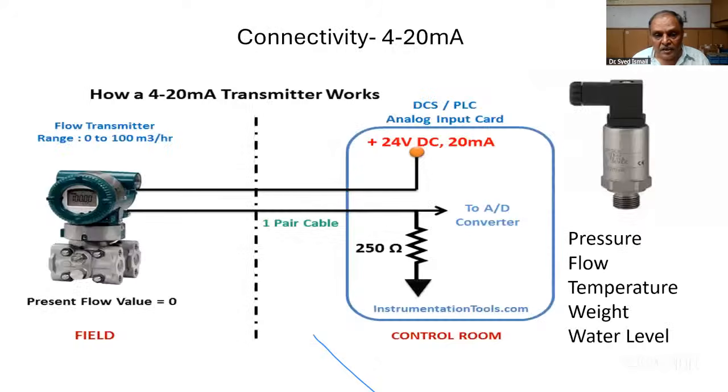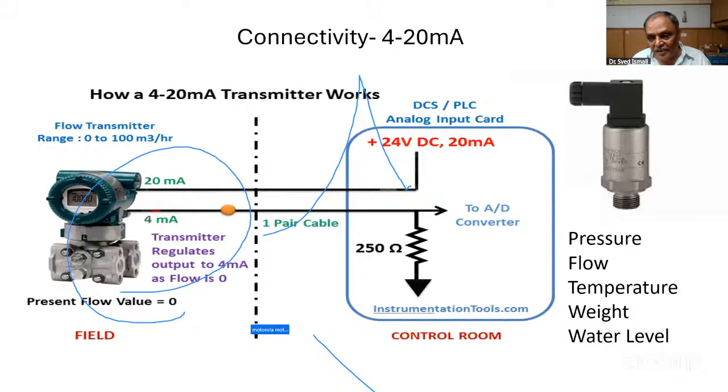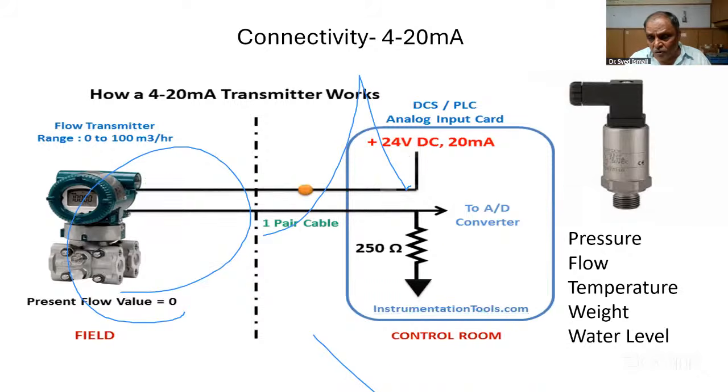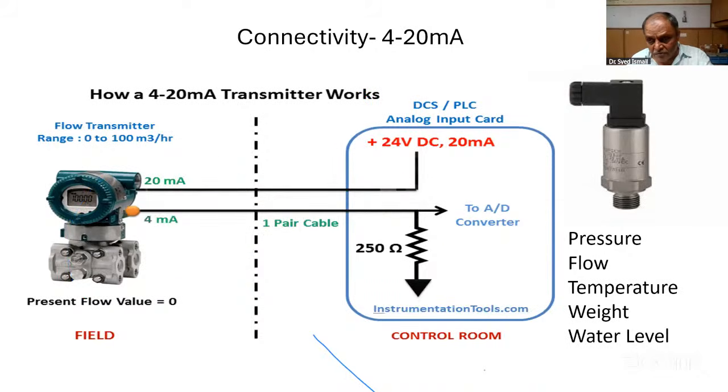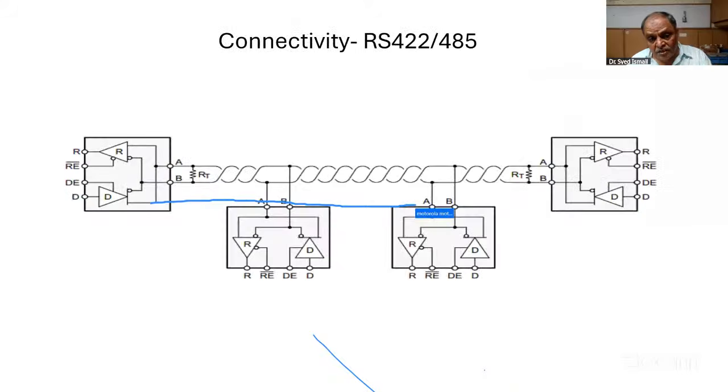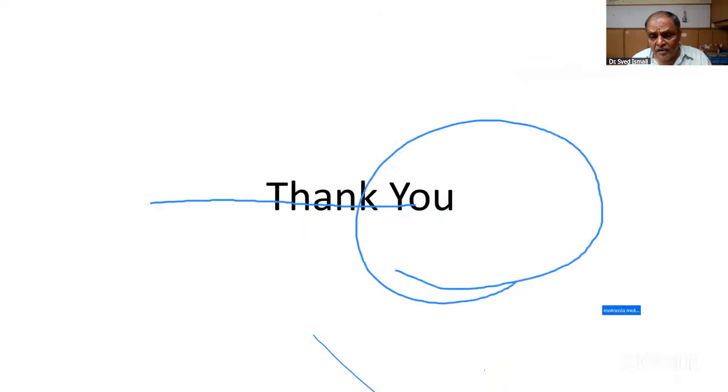You'll get quicker results. For example, this is the diagram that goes 4 to 20 milliamperes. All the field instruments, oil industry, every industry, use 4 to 20, because the power also goes from your main place through the wire and comes back. In this, it's 100% sure it works. Pressure gauges, flow meters, everything is there. In agriculture, we don't find them much. At least in Asia, very few people are working with flow meters with 4 to 20, or it can be RS-232. I'm not explaining RS-485.